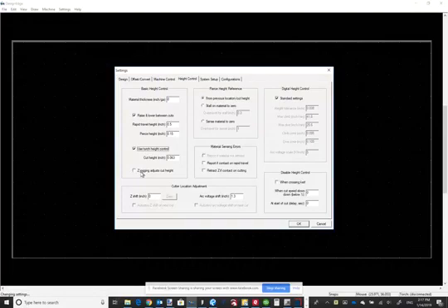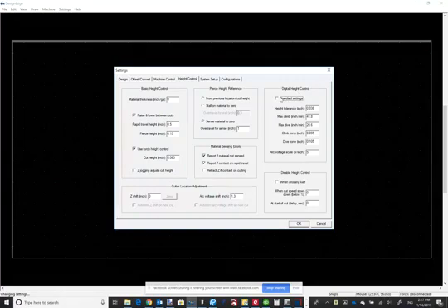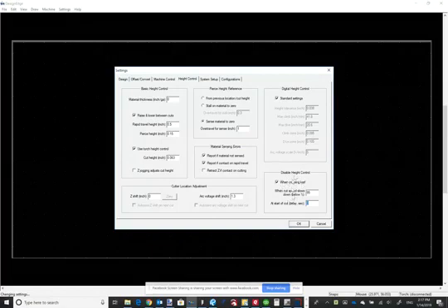This is that Z jogging adjust the cut height. You can sense the material and you can have it give you those warnings. You can uncheck this and muddle about with these settings. And you do want to put something in here. So that's the big difference between advanced height and basic height. It adds this disable height control box that I find to be very important, and the ohmic sensing that goes a whole lot faster and establishes that pierce height much more reliably.